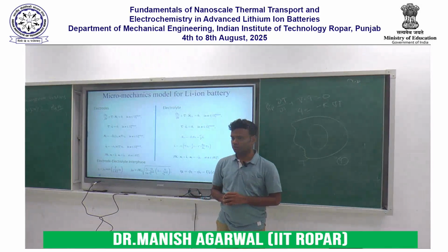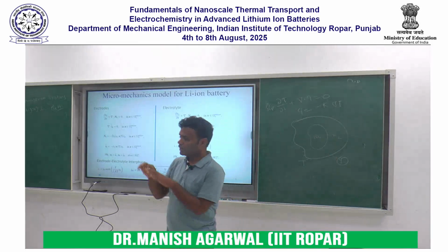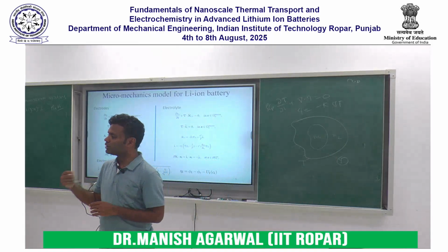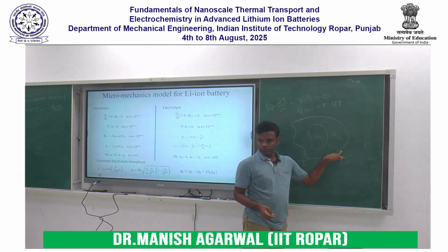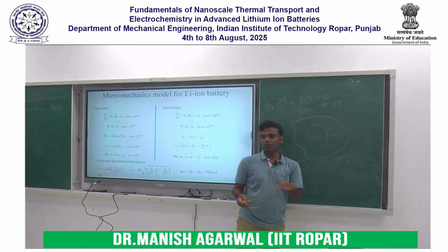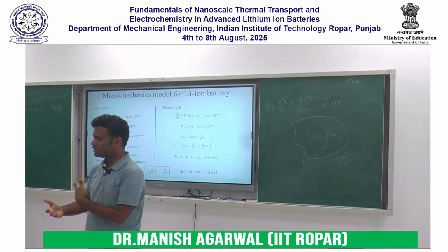And the thing I wanted to highlight is, let's say for whatever reason there is a bit of heterogeneity in the domain, okay? So it is of material 1 and this is material 2, right? So apart from the boundary, now there is a new thing in the problem, and that is the interface between the two domains, right? So apart from the boundary condition, we need what are known as interface conditions. What is happening at the interface, right?